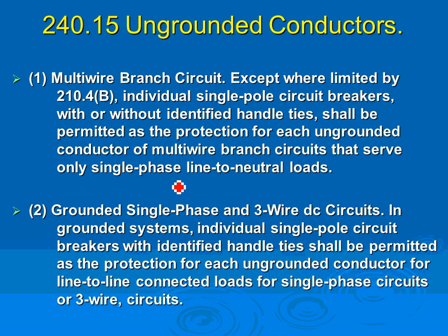If you have single phase circuit breakers, you tie them with an approved handle and you can feed a multi-wire branch circuit, 277 or 120, no problem. If you have 2-pole circuit breakers, you tie them with an approved handle and you can make them feed 240 loads, like air conditioning in a house. That's approved.